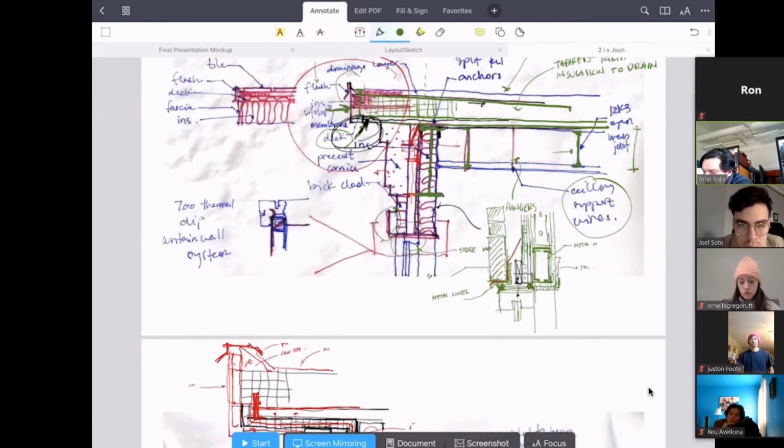So I cannot bring my metal stud wall all the way up, because that Y flange right there is in the way. That means I'm going to stop my metal stud wall right underneath that, and I'm able to fasten that. Then I have to think about what happens here. That thing is sticking out, and you have a ceiling. If you have a ceiling, that means you're trying to hide what's on the wall because you brought it all the way up. So I need to think, how do I hide that? What would be my options?